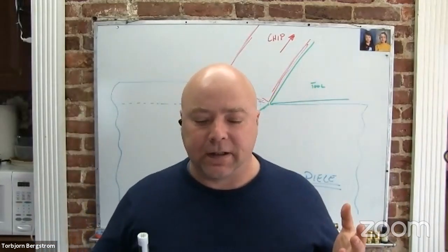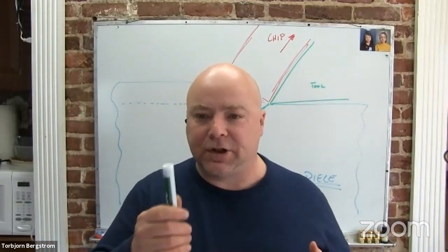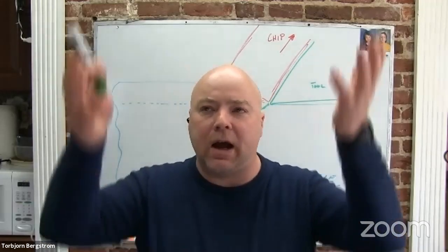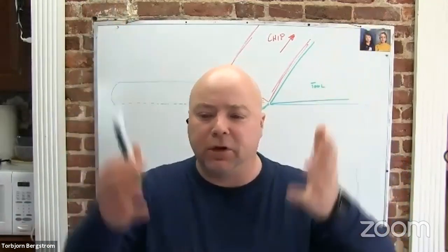Now, it's interesting because often we get that chatter situation when it's not that we've got too high of a cutting force, but sometimes it's when we've got too low of a cutting force.